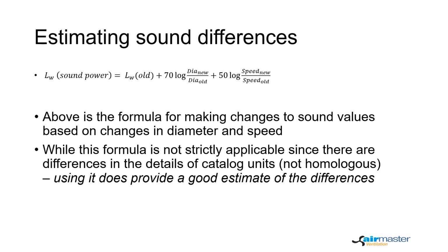Sound pressure is what you actually measure, and dB is a logarithmic scale that allows for a huge range of actual numbers. Sound power is a property of a machine in that it is the power the machine creates as sound. At a given size, speed, point of operation, this is a known quantity.